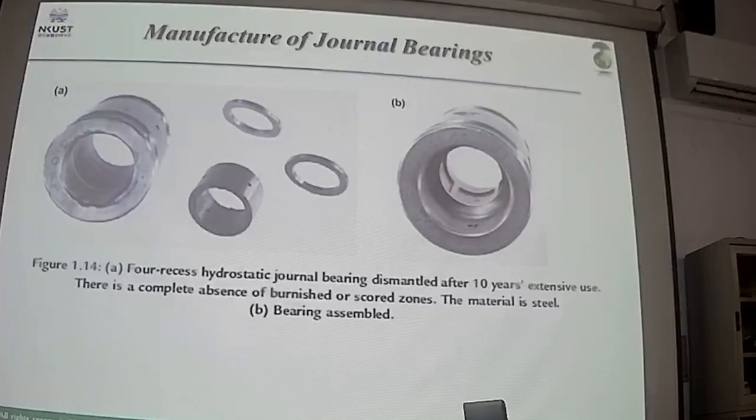So usually, if you can design a good hydrostatic bearing, there's no touch for the bearing part. So it operates separated by the fluid, either oil or gas. So free of the touching, so there's no wear for the machine part. And so usually it can operate a very long service life.